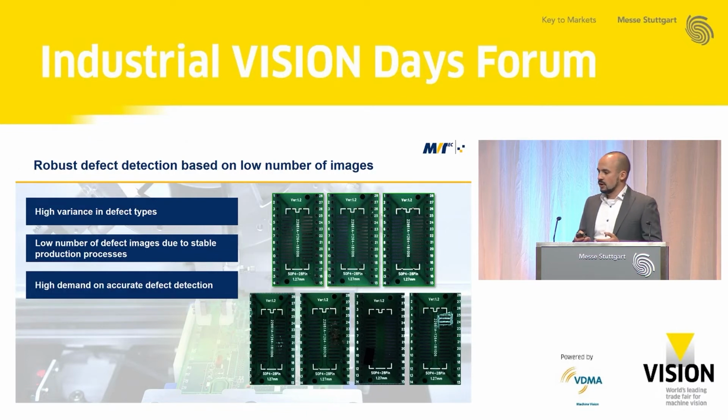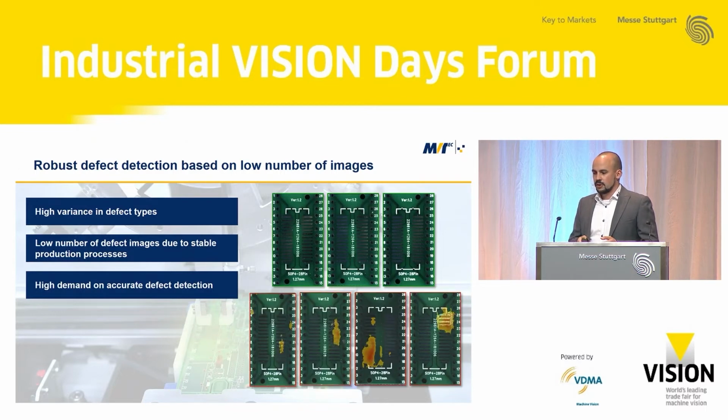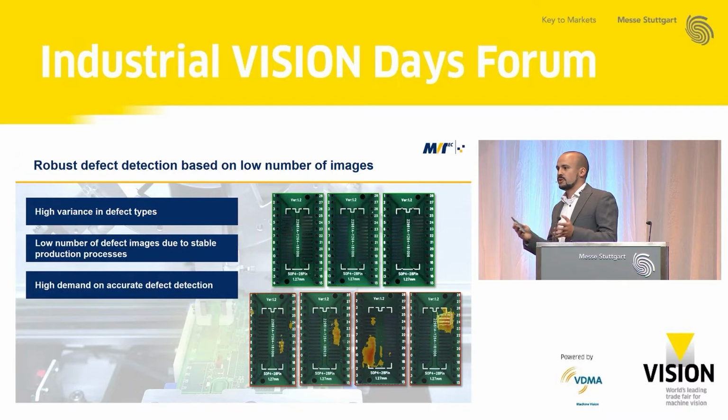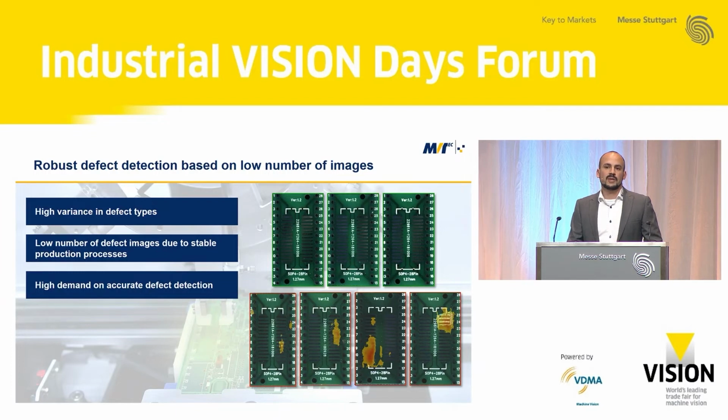In the images on top, you see 3 images without a defect. And basically, these are the kind of images which were used for the training of this anomaly detection. So the challenge that there is no defect image is not a problem for this technology, as you only need good images. You train with good images, a number of 30 to 50, and then you can have results like shown in this example, where the defects can be reliably detected, and even the areas where the defect is located can be highlighted.